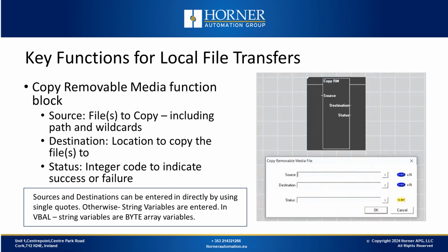If you use variables for the source or destination or both, then for variable-based advanced ladder, these will be byte array type variables, and for register-based ladder, these will be register references, which can contain up to 2 characters per 16-bit register. So if you had a string of 10 consecutive registers, that would give you the ability to handle a string up to 20 characters long.